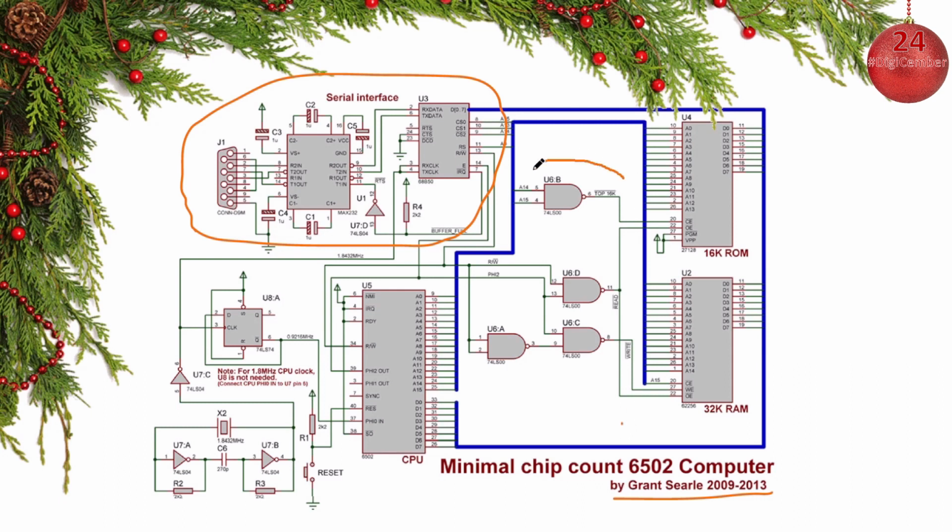lines over here, and he has also done something you see here for the read-write signal. It goes into this chip here for read, and it goes to the write enable, and it also goes to the output enable, so when you are putting this low, this chip won't be connected, but this will be able to read.